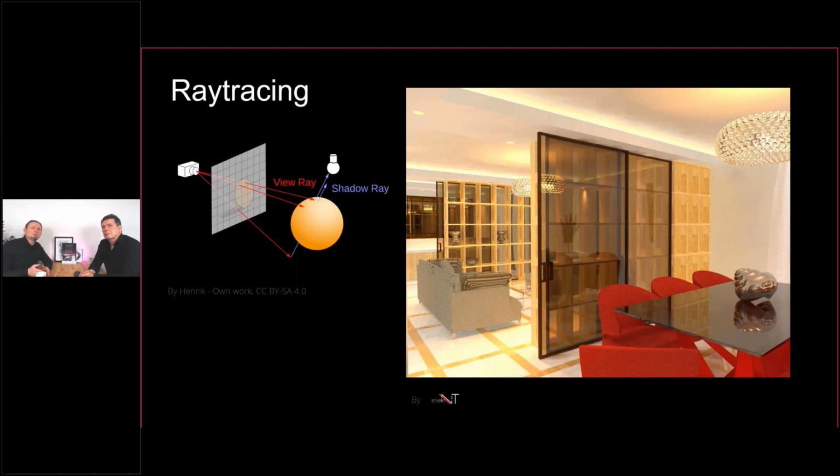You can access this by the calculation options. You can also enable or disable ray tracing. It's not switched on by default. It's switched off by default, because it takes more time than radiosity to calculate these effects with transmission and reflectance. But the special thing about the RELUX ray tracing calculation core is that you can also obtain values for illuminance via this ray tracing method.